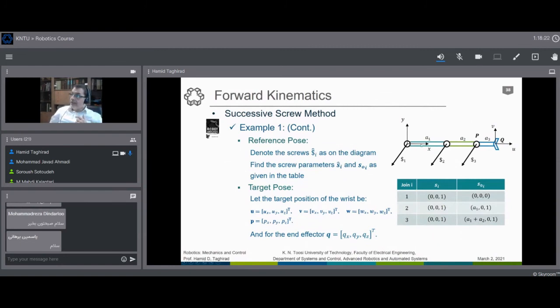So we just get the direction, the difference that this S1 vector has an offset of A0, which is the link length. We had before defined it as a link length, but here we call it the S0 variable. I'm very sorry to have a typo here. So we have A1, 0, 0, and A1 plus A2, 0, 0 here in terms of that. And everything is done now.